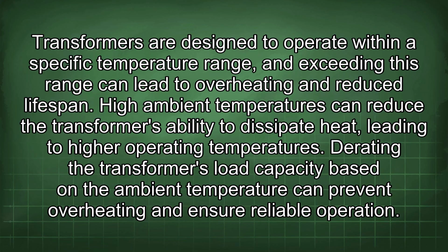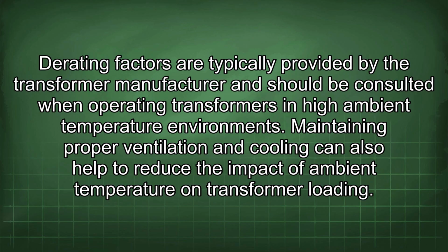Derating the transformer's load capacity based on the ambient temperature can prevent overheating and ensure reliable operation. Derating factors are typically provided by the transformer manufacturer and should be consulted when operating transformers in high ambient temperature environments. Maintaining proper ventilation and cooling can also help to reduce the impact of ambient temperature on transformer loading.